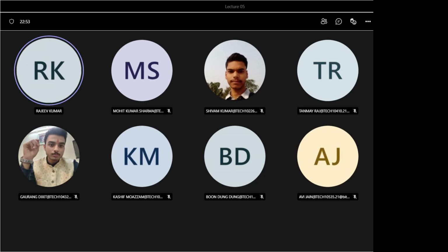Okay, so you have seen reaction force has only one component, and that component acts vertically to the support on which the roller rests. So when roller support is there, only one reaction vertically upward will be there, and for balancing of that one also downward force will act. When it is hinge or pin supported, two components of forces will be there.